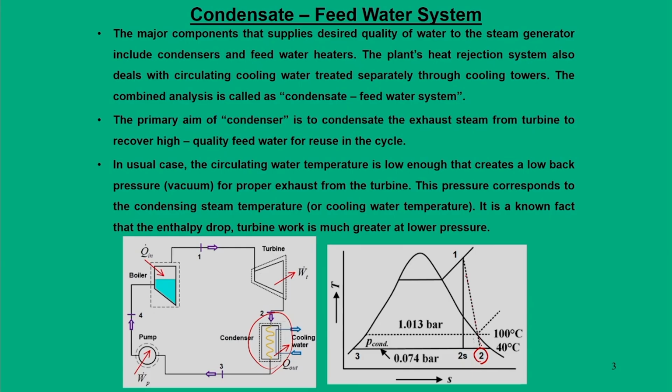The second requirement of the condenser in the steam power plant is that the output from the condenser is again fed to the pump and it gives the necessary feed water to the boiler. That is the reason we also require a feed pump that takes the water from the outlet of the condenser, which we call the condensate, and then gives it to the pump for a higher pressure. The pressure of the water reaches the boiler pressure. So, this is the main requirement.